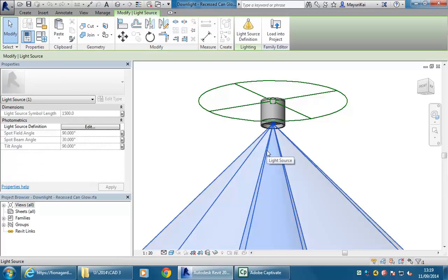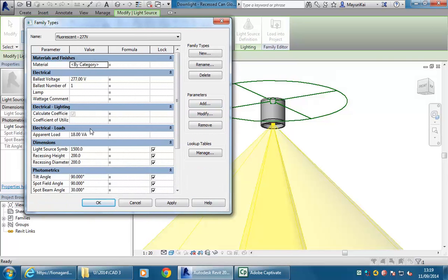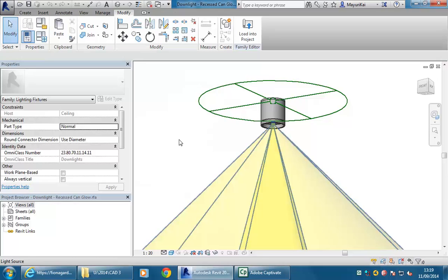So if you instead treat them as individual families, each light source, and the reason it's set up like that is because basically when you go to adjust the light's brightness, these parameters, which I'll come back to, these are the parameters you use to control the brightness and the other properties of your light, they're set to operate on this light source element.